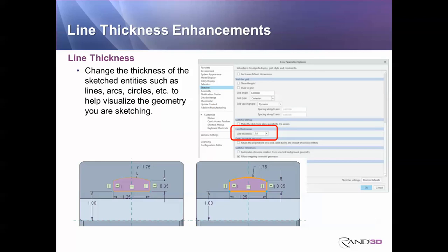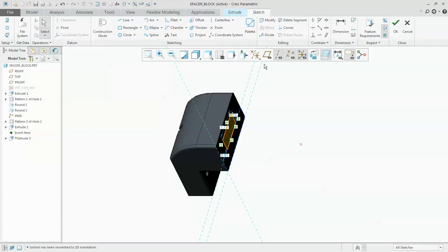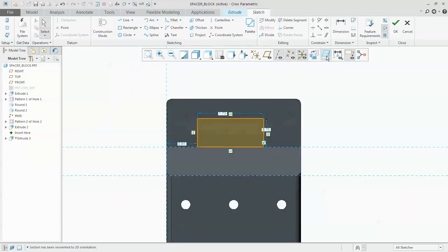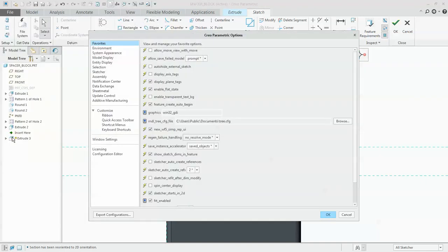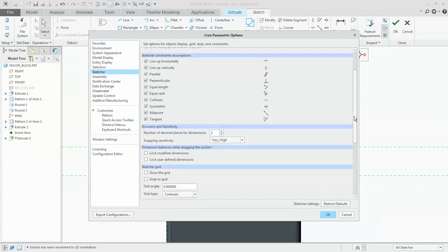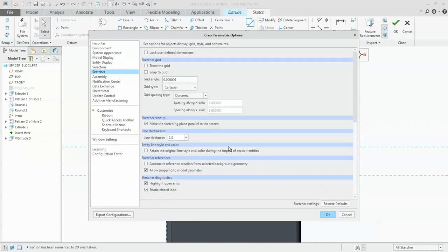You do have the ability to change the thickness of your sketch entities to make it a little bit easier to see. In some cases, perhaps you prefer to see a bolder representation of the sketch lines. So if you like to do that, for example, you can go into the File Options environment when the Creo Parametric Options box launches. Look for the Sketcher category, and then from there, you may have to scroll. You should be able to access the line thicknesses area where there's a line thickness value collector where you can specify the line thickness. Of course, if you prefer, you can automate that globally with the config.pro option listed in that note menu.